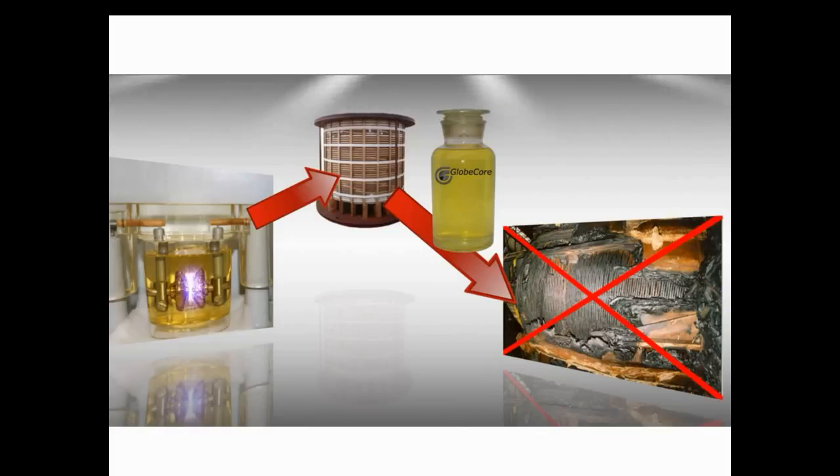Any servicing company works with the oil. Let me briefly remind what oil does. It provides dielectrics, which is insulation. It protects paper insulation and provides cooling. Paper insulation is extremely important now. Notice, all the time we are talking about the paper, as it is the weakest point in a transformer. So, as we can protect the paper, we make a transformer operate longer and save money.